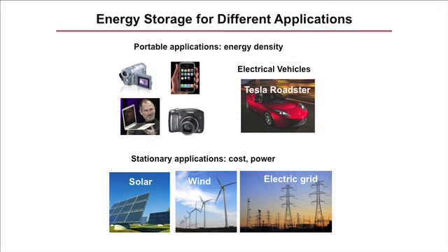Anything related to energy is so application oriented. You've got to understand what the application needs first before you go do your research. You want to know what the parameters are. That's most important. You want to tune those parameters. Let's look at portable applications. As I said, it's the energy density and specific energy, the energy per unit weight or volume, that's important as the first parameter before you talk about other parameters. Of course, the cost is also important. The reason is very simple: you carry this device with you, so the size and weight are important.